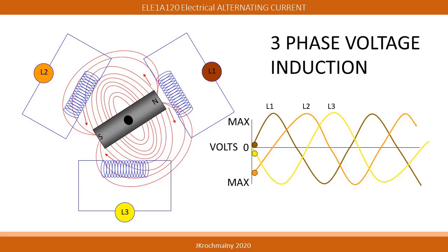Starting at the 0-degree mark, notice the position of the flux lines in the L1, L2, and L3 capture conductors. Relate these flux line positions to the measuring graph located to the right. L1 has 0 volts, L2 has close to maximum volts, and L3 has little volts.